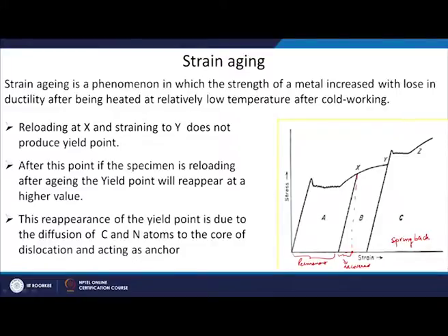So, if you are designing a part, and suppose you have designed by the total strain, so that after deformation its length should be this much, and it is going to be attached to another part, which is also attached to another part, this is the strain you wanted in the material after deformation. Suppose you take the total strain. What will happen? There will be some recovery. So, you will find after the deformation that the length of the part is smaller than what you wanted to attach. So, if you want this much strain in the material, always deform to a higher extent, so that you can get this much total strain. And how can you get this line?